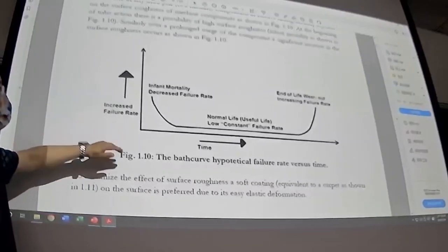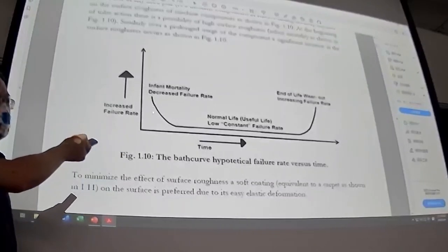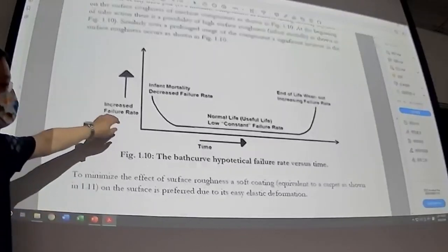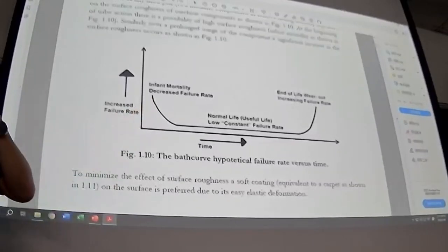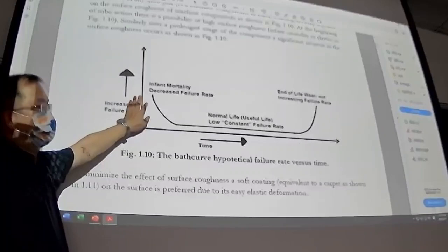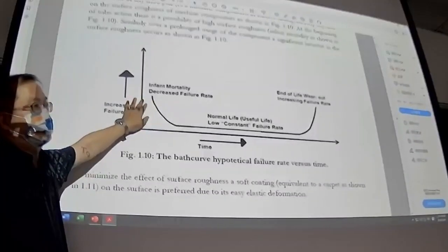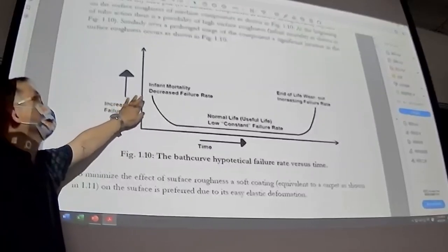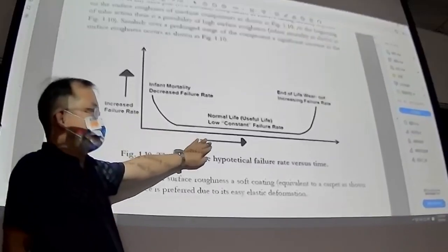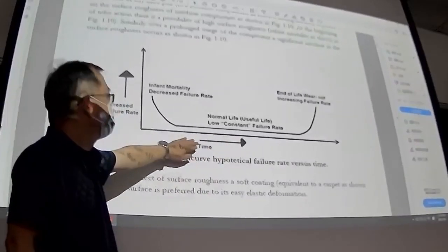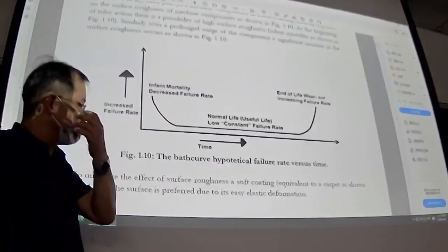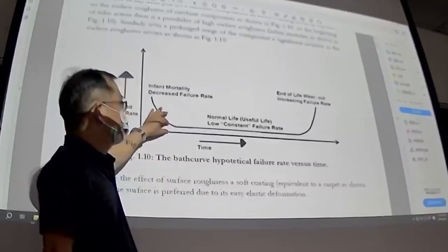Okay, so in the beginning you have a very high failure rate because all the mechanical components are new, and they need some specific time to run in. Okay, so in the beginning the failure rate will be high, and gradually as the service time continues, the failure rate will drop to a stable, low rate.